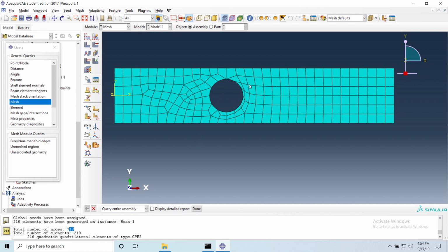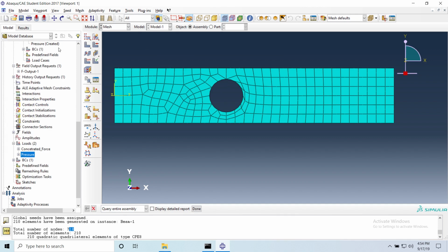I know that it doesn't look like you're going to get super good accuracy in this one, but we just want to run and then post-process the results, okay? Even if our answer is not going to be right. And that is something that I ask you to do during the homework. You're going to try 4 or 5 different mesh densities. How refined your mesh is is called mesh density, so going from 100 to 10,000 elements. And then you're going to see how your solution converges when you increase the number of elements. So that's something that you're going to have to study during the homework.